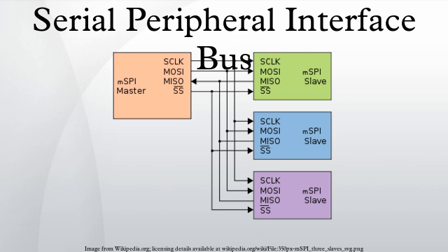JTAG is essentially an application stack for a 3-wire SPI flavor, using different signal names, TCK not SCK, TDI not MOSI, TDO not MISO. It defines a state machine, protocol messages, a core command set, the ability to daisy chain devices in a scan chain, and how vendors define new commands. The devices in a scan chain are initially treated as a single device, and transitions on TMS update their state machines. Once the individual devices are identified, commands may be issued that affect only one device in that scan chain.